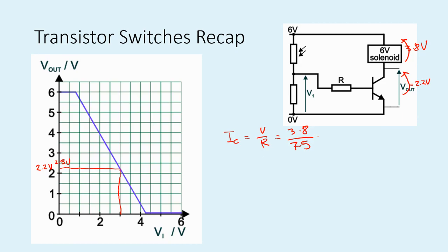So that's quite a large current of 0.506 recurring amps, or 506 milliamps. We can then use P equals IV because the collector current is pretty much the same current that's flowing to the emitter, because remember the base current is 200 times smaller, so basically ignore it. It's not nothing, but we can ignore it fairly safely. It's not going to have a massive impact.